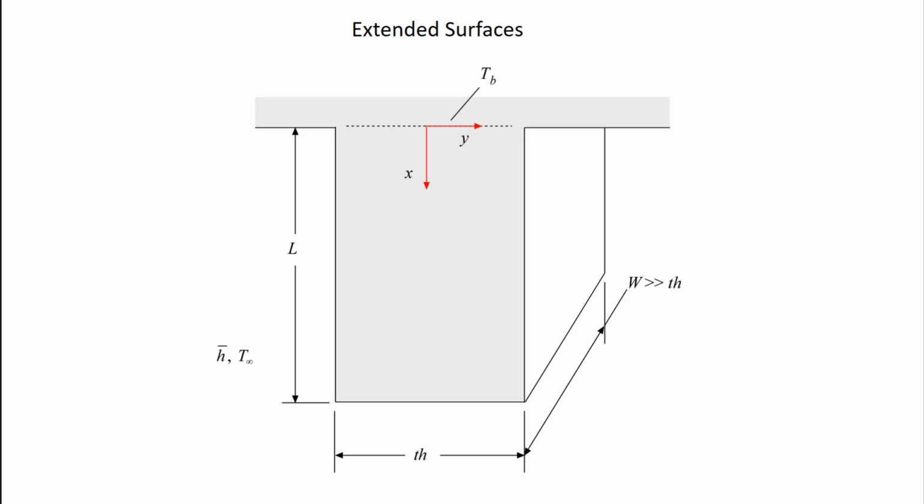problem, right? If I imagine what energy has to do, so let's see here. If I am a piece of energy and I start my travel right here and I want to get out, what do I have to do? Well, I have to move by conduction both in the x direction but also in the y direction, right? And that gets me to the surface, and then once I'm at the surface, then convection takes me to the surroundings.